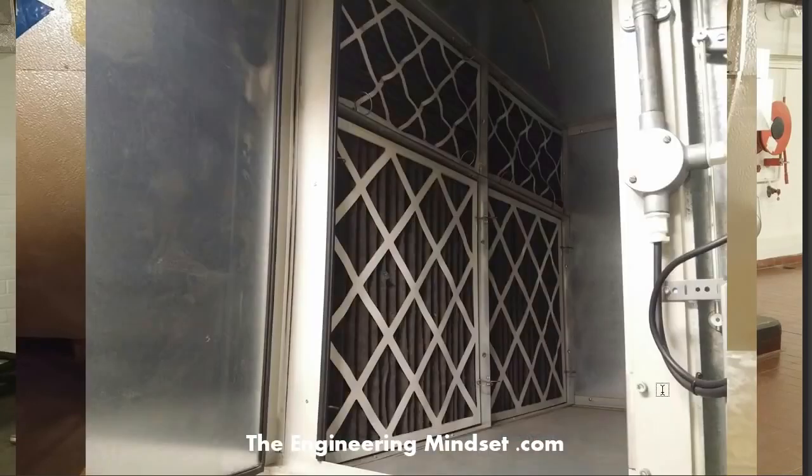And just to give you an example here of how that would look inside the AHU in real life. So we've got 4 panel filters of different sizes, obviously, slightly different design here by a different manufacturer, and also the material that is used, the thickness. Or the thickness of this filter material is what's going to capture the most dirt and germs, etc., that's going through there. And the AHU designer, and you can even bring filter specialists in, and they will advise you what filter material you should use. There's some standards which you can look up and read as well.